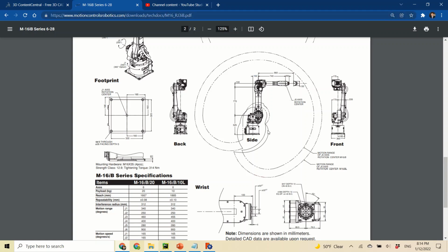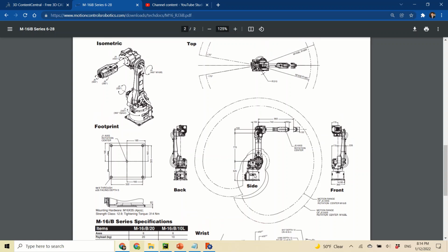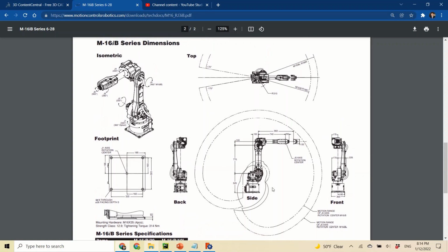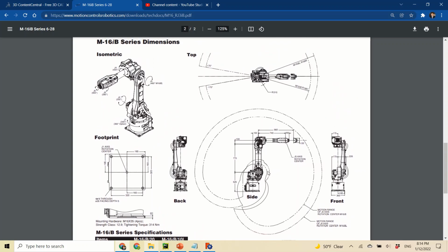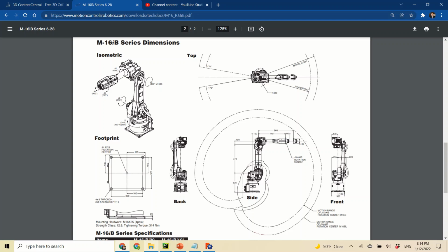The robot coordinate system is this direction is X, towards the Y direction, and the top is Z direction. It follows the right-hand convention. So we need this data to figure out the coordinate offset between each joint and the base.